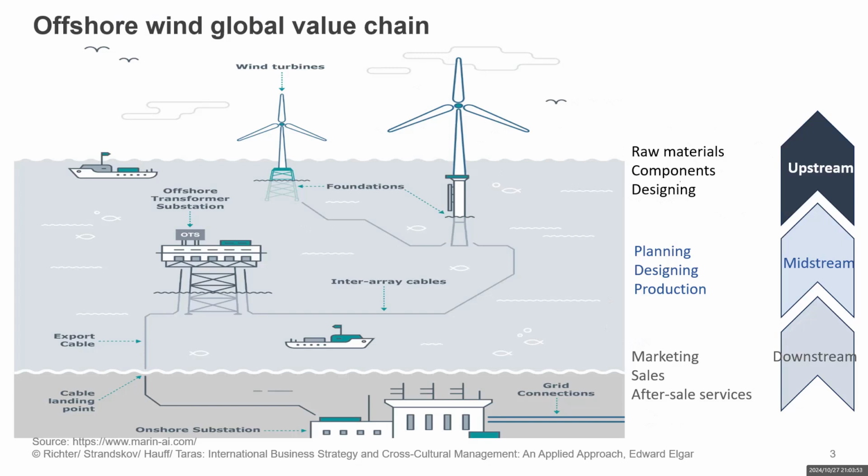And then the midstream stage includes, for example, installing the turbines, anchoring the turbines to the seabed, using foundations to ensure their stability, and connecting them to offshore transformer substations via the inter-array cables. And then here the voltage is elevated, and the elevated electricity will be transmitted through the export cable to the cable landing point. Here it marks the transition from underwater to underground cables, and the onshore substation would connect the export cable to